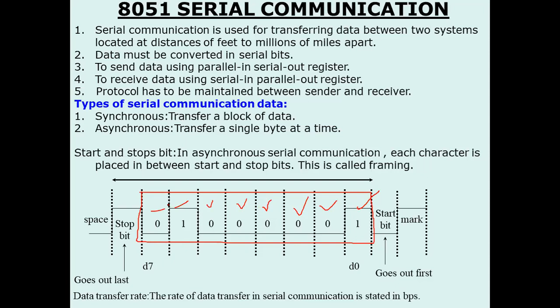On the receiver side, first this 1 will be received and stored into the SBUF register, then 0 0 0. As the sender keeps sending, from the right hand side to the left hand side, those bits will be stored serially. Clear or not? Yes, sir, clear.